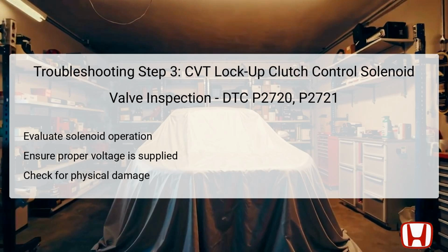If these inspections reveal normal functioning, you may conclude that the solenoid is operating properly. However, if there are anomalies, this valve should be replaced, as it is pivotal for the lockup feature to function accurately, which directly influences the overall transmission performance.